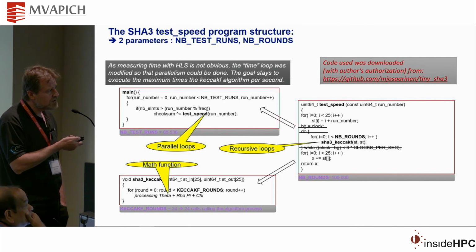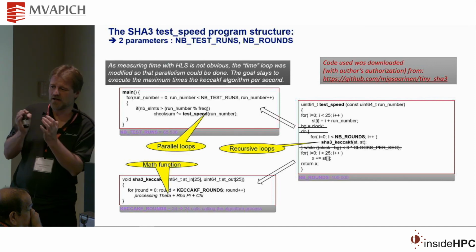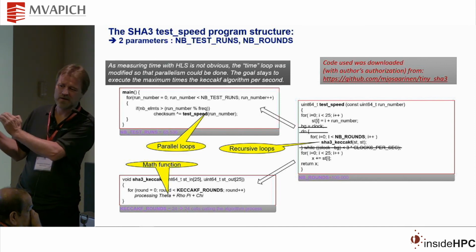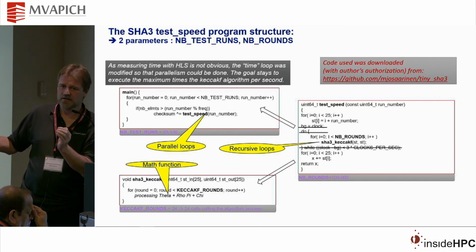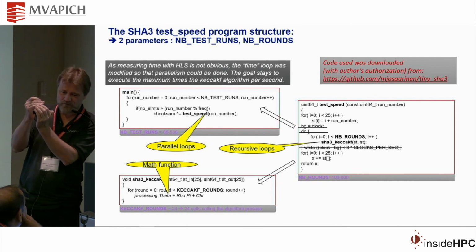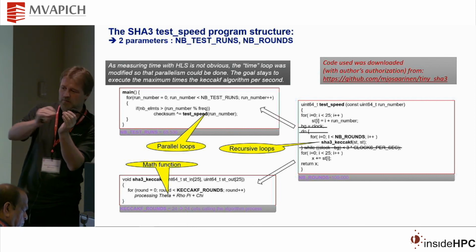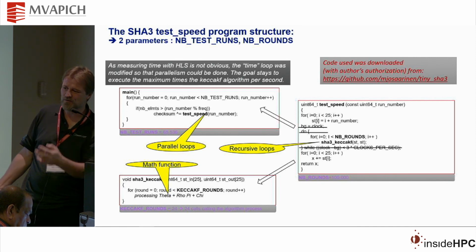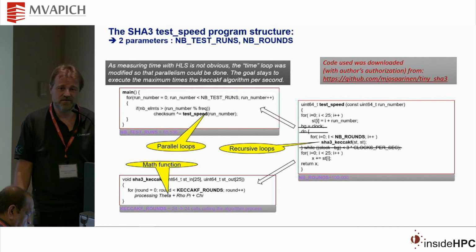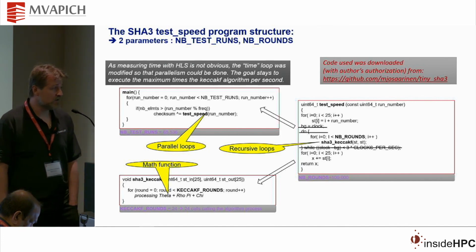Anytime we check whether we have recursive or parallel loops, it is very interesting, because in hardware you just need to duplicate the hardware. If you have a loop that executes something like 20 times things that are completely independent, in software you wait for the first one to be finished and you execute sequentially 20 times. In hardware, you just say, hey, parallelize as much as you can. So the more you can parallelize in hardware, the higher your acceleration factor. This is how you can achieve a times 35 acceleration with hardware.